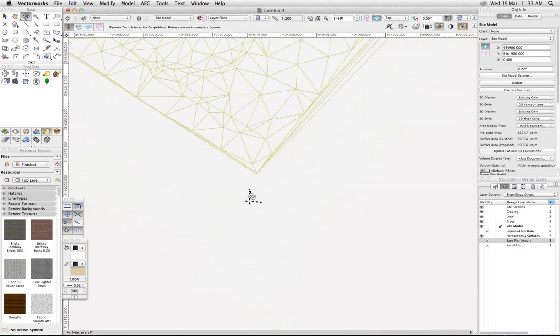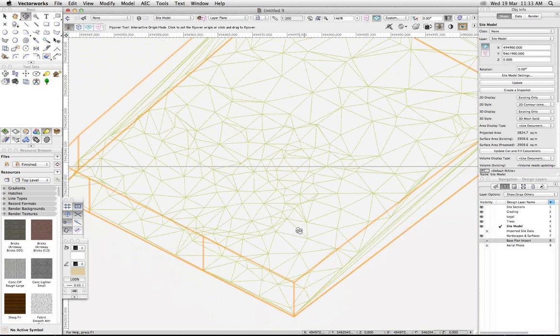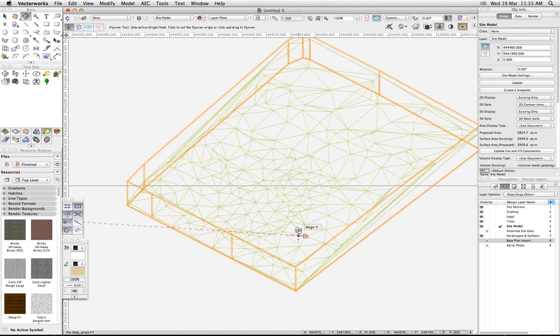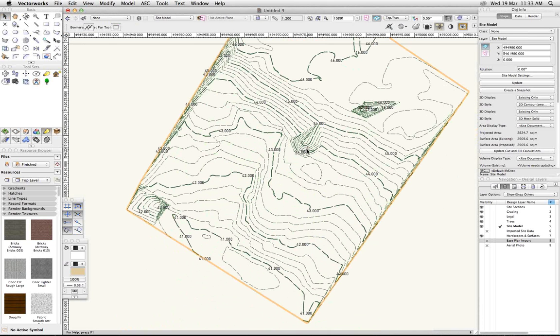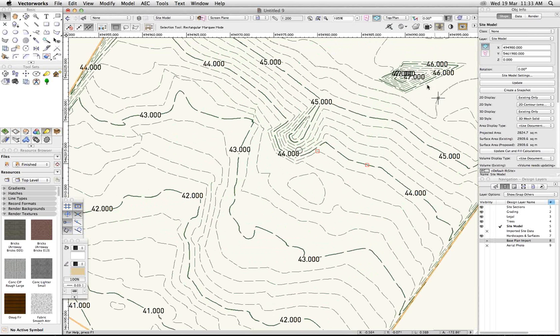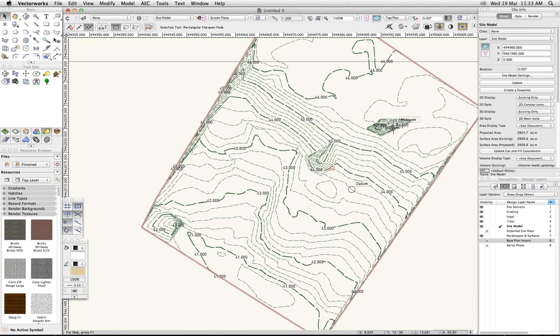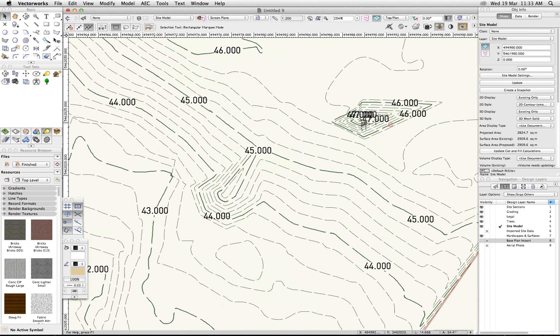Okay, so that was pretty smooth and pain-free, and without me talking through the process, you're really only about 10 minutes in at this point. Now, even though that was pretty straightforward, there is some cleanup that usually needs to be done. Some of it we can see here just looks kind of suspicious. Like, what's this little hill here, and what's this little hill here? If we dig in a little deeper, we will probably find that there were some elevations that were things like top of sign or top of post, and it's extraneous data as part of my site model. It's not actually a hill.